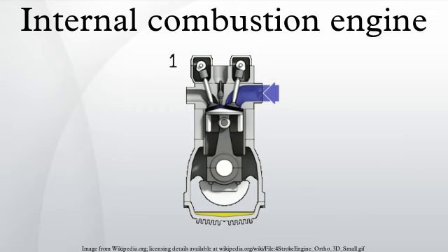Oxidizers. Since air is plentiful at the surface of the Earth, the oxidizer is typically atmospheric oxygen, which has the advantage of not being stored within the vehicle. This increases the power-to-weight and power-to-volume ratios. Other materials are used for special purposes, often to increase power output or to allow operation underwater or in space. Compressed air has been commonly used in torpedoes. Compressed oxygen, as well as some compressed air, was used in the Japanese Type 93 torpedo. Some submarines carry pure oxygen. Rockets very often use liquid oxygen.